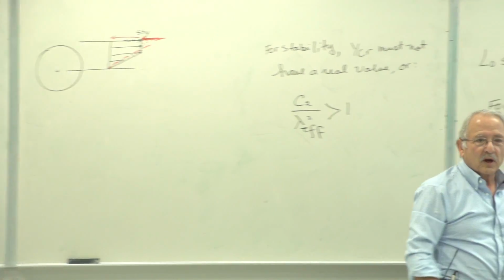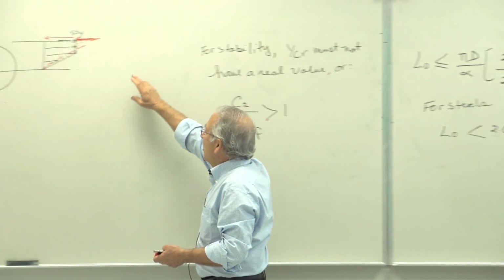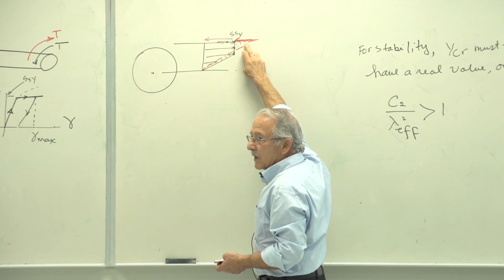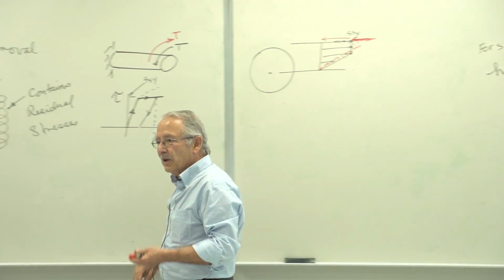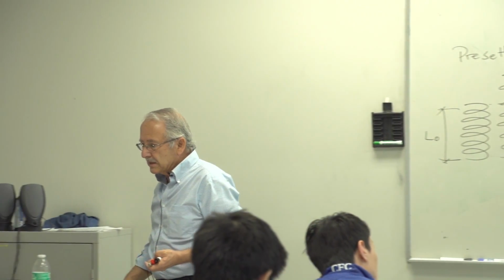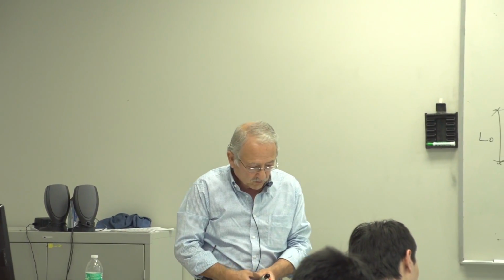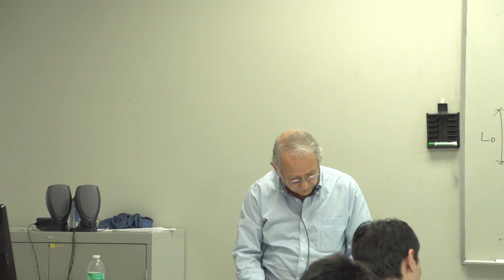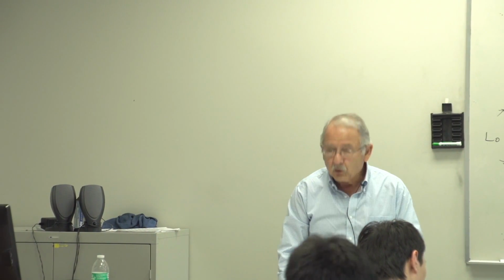Therefore, now when you apply that load, first you have to overcome that. And then you load the material. And that's why the material becomes stronger. So that's the reason why we do set removal or presetting. Any questions?